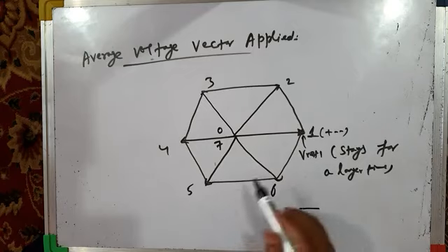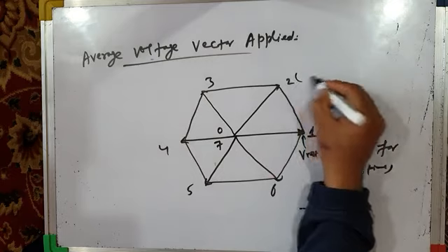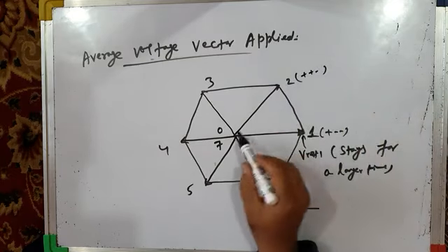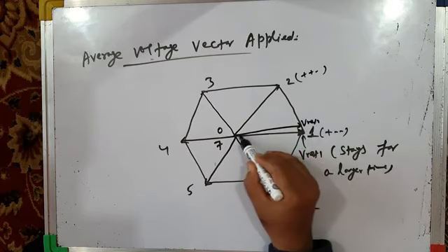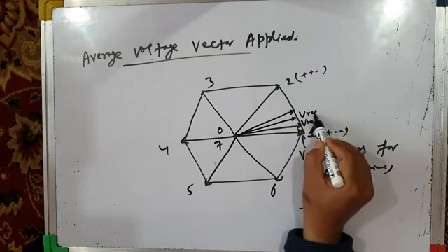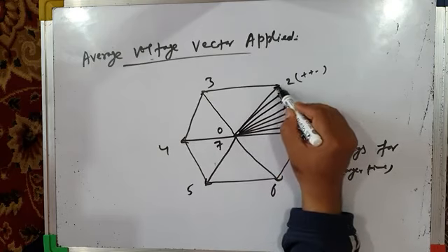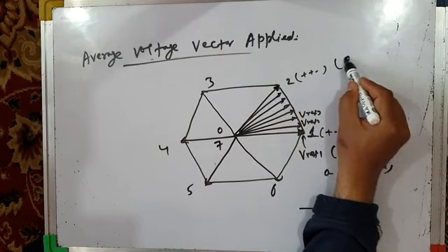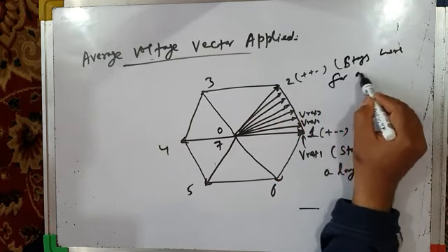And then switching between 1 and 2 occurs. So active vector 1 is applied, then active vector 2 is applied, and time averaging of the two produces, in one sample, reference vector vref 2. Then vref 3, vref 4, depending upon how many samples you take. And finally, when it reaches active vector 2 along this, it remains or it stays here for a long time.